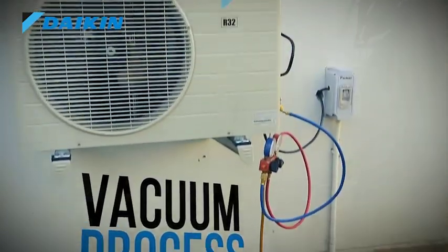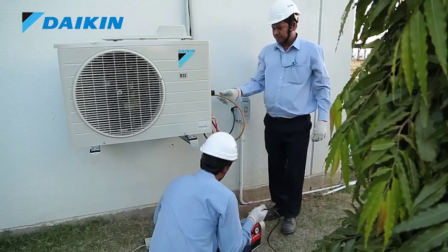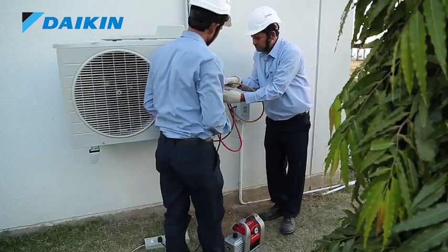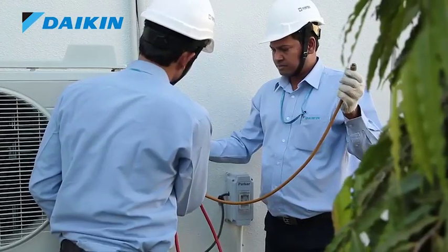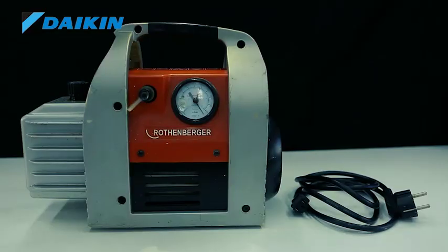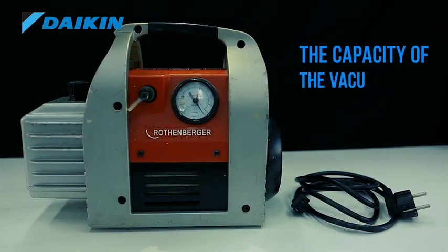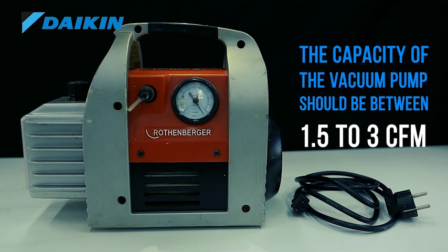Vacuum process. After the leak test, vacuum the pipes through vacuum pump to remove moisture, air, or other non-condensable gases. Presence of these impurities will lead to improper working of product. For vacuum process, ensure that the capacity of the vacuum pump should be between 1.5 to 3 CFM. Also ensure vacuum pump should be double stage and properly maintained with right amount of oil.